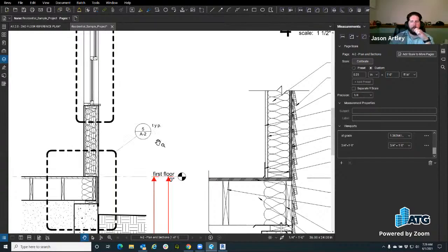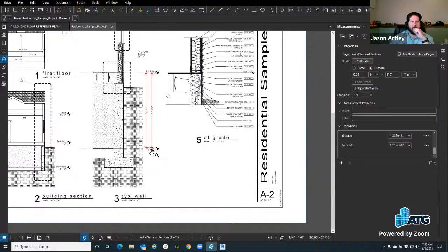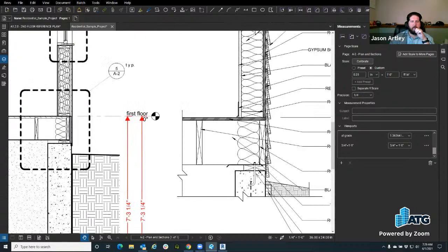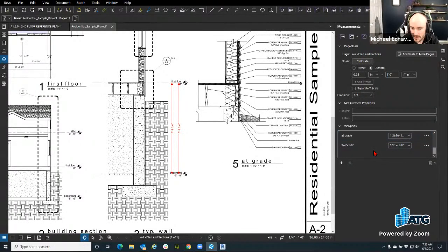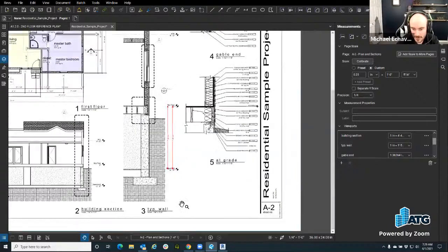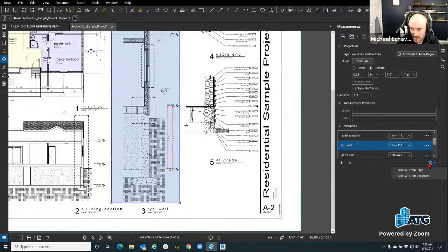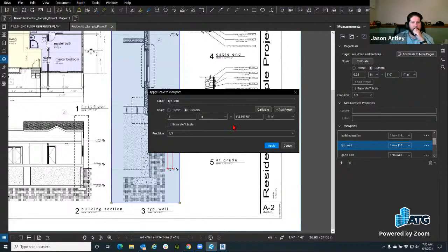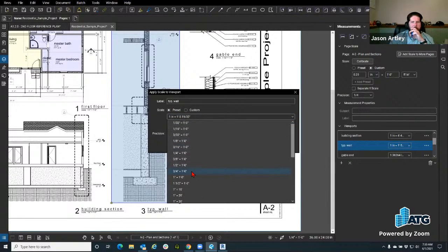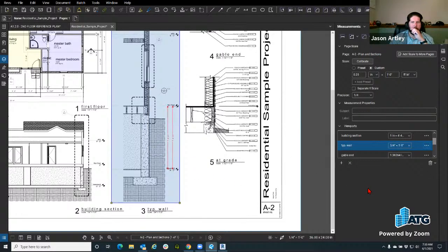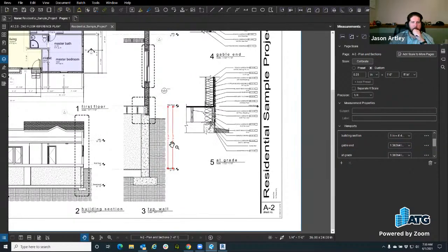You have multi-views for that measurement. What do you mean by that? Multi-views. It may be because there's multiple measurements here for this. What is this typical wall? Maybe that's why the measurement's off. Oh, yeah. So maybe that's not the right scale. Yeah. See? But you can delete them right there in that lower right-hand corner of the measurements panel. So you can delete those views. That's probably what's going on there. Good eye, Chris.